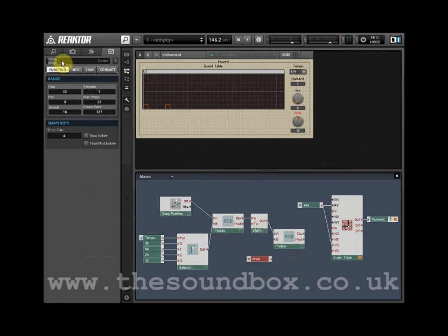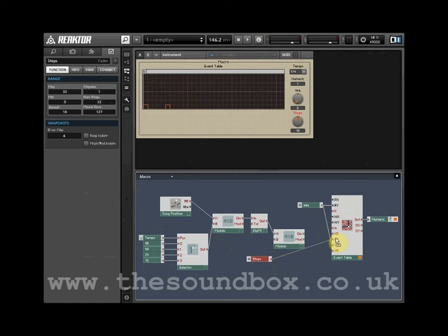The XR input controls the amount of X rows in the event table, so let's wire our knob into the XR input of the event table. By connecting the Steps knob to XR, we can control the length of the loop. We need to divide the event length by the number of steps in a loop cycle. To do this, we need to wire our Steps knob into the second Modulo module. The output from the Modulo needs to trigger the read position. Wire the mod output into the RX and R input ports of the event table.